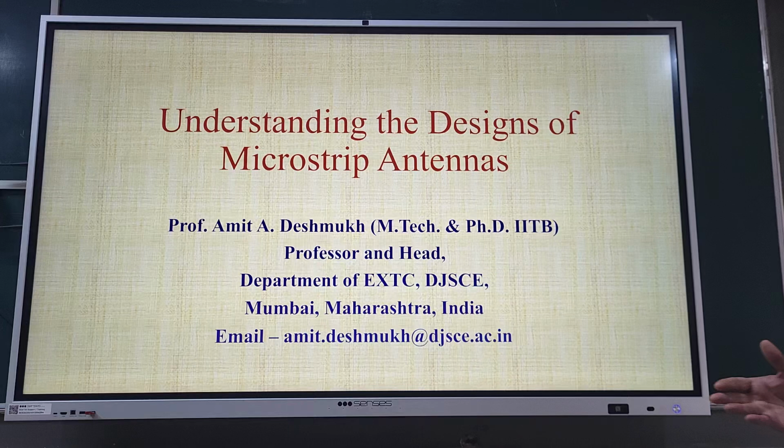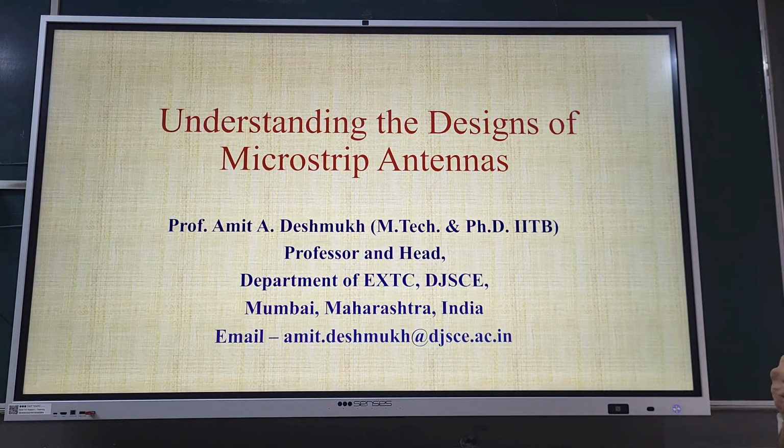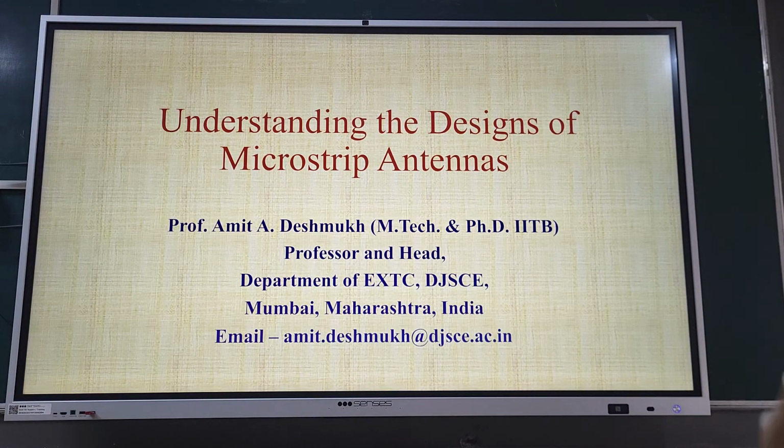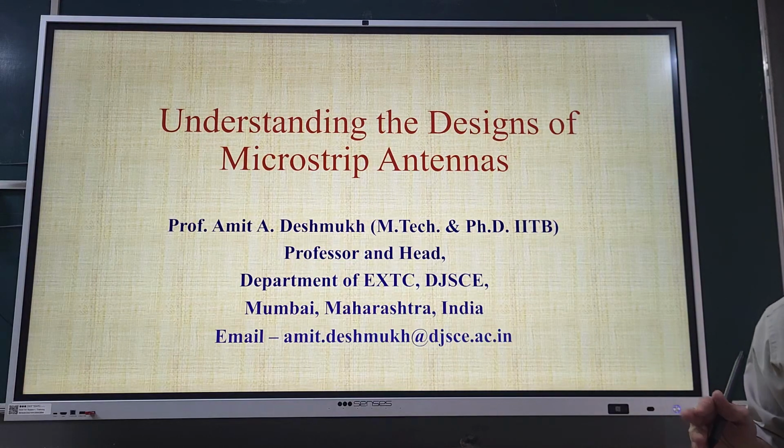In the literature, whenever you are designing a wideband antenna, a circular polarized antenna, or a defective ground plane structure antenna, you do some modifications in the patch geometry. So when you do the modifications in the patch geometry, alterations between the interspacing between the various fundamental and higher order modes of the patch take place, that realizes the respective response.